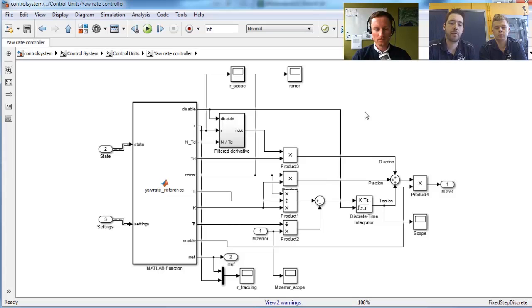But of course, the friction for your wheels is limited. You can't apply an infinite amount of torque on there. Which means that the actual yaw moment on a car is not always as big as the commanded value. And if you use a normal PID controller, this can give you problems with wind-up of your integrator.